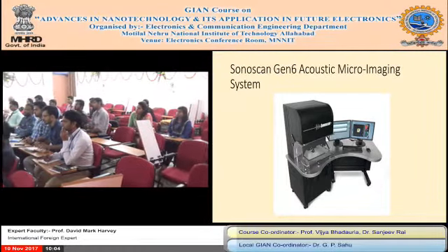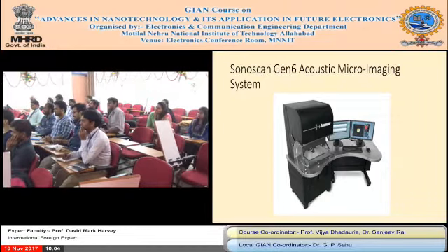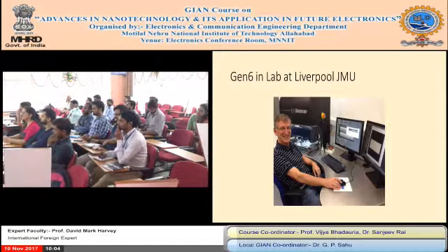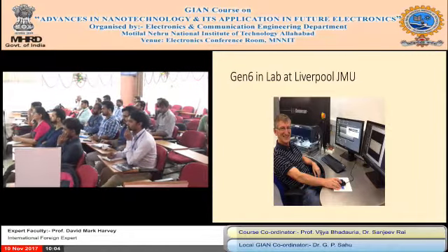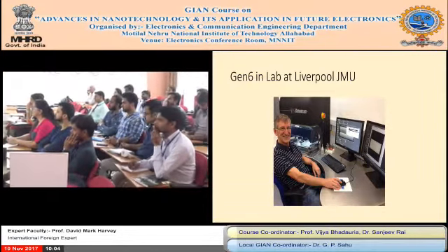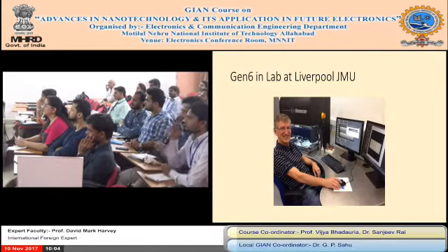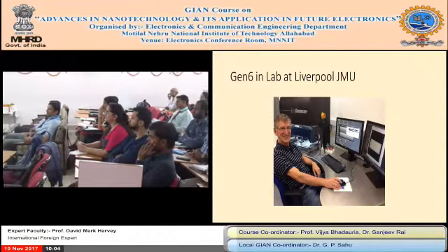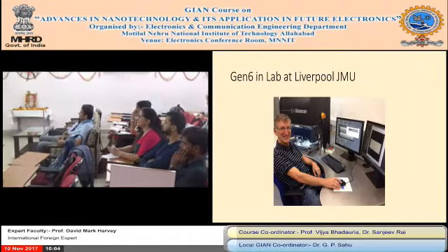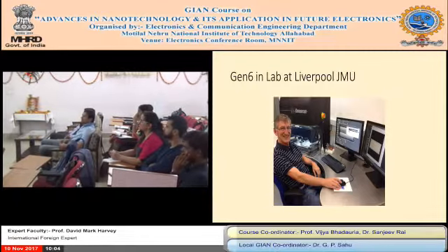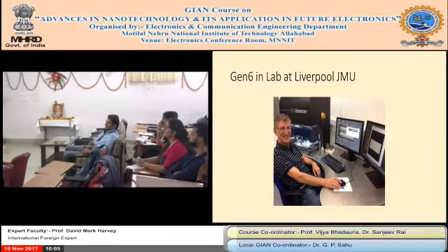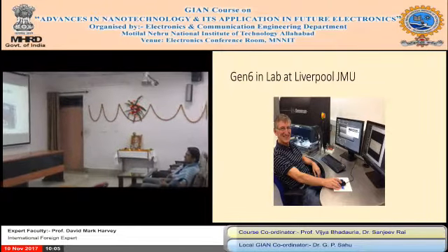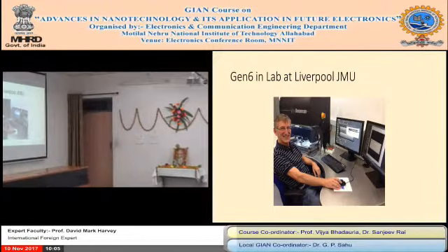So there's yours truly, sitting in the lab, having negotiated a very nice price from a company, because being a university we can buy at an educational discount. And we have a very good relationship with the company Sonoscan, which is an American company, but they have a sales office in the UK. So there's the scanning system there. Inside there is a water tank, and then we have a head we can put different sensors in, and it moves in raster fashion, very mechanically based, up and down, but very accurate. The scanning in X and Y is probably better than 1 micron.